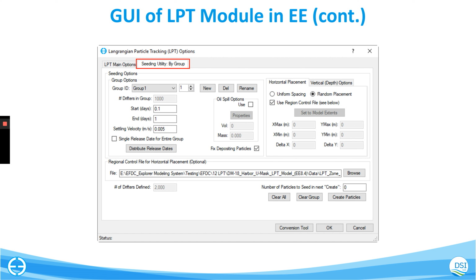That's because when you hit Create Particles, it's writing all that data out to the file. I think we should be adding in the near future an ability to update a particle group. But for now, if you wanted to change any of those properties of the specific particle, you'll need to recreate the group.